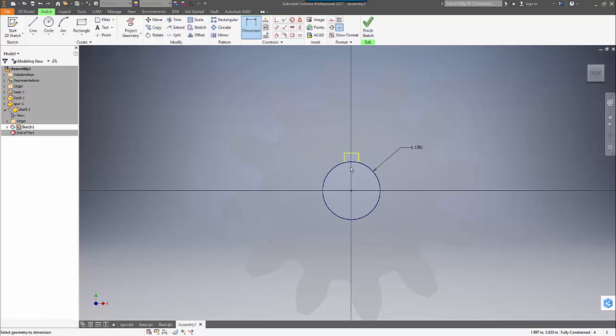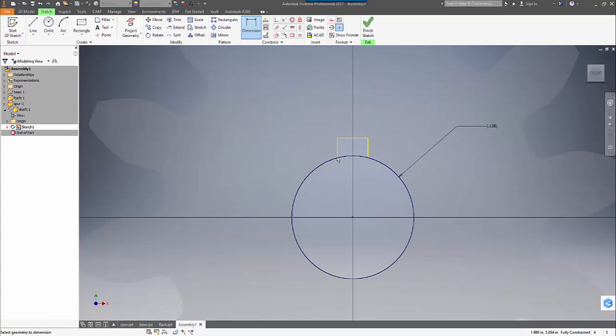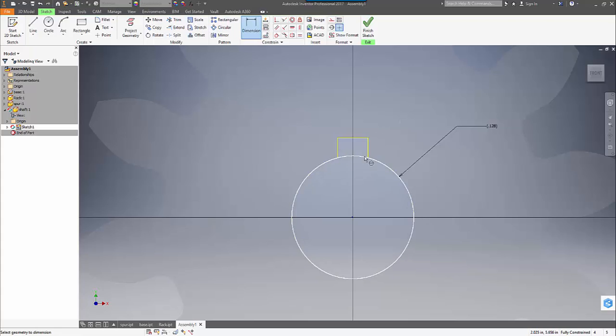So the second thing that we have to do with this shaft is we need to cut in a keyway. And so we could do one of two things. Actually, I'm going to use a technique which is going to mirror this keyway into the shaft, and then we'll utilize that as the actual drive.